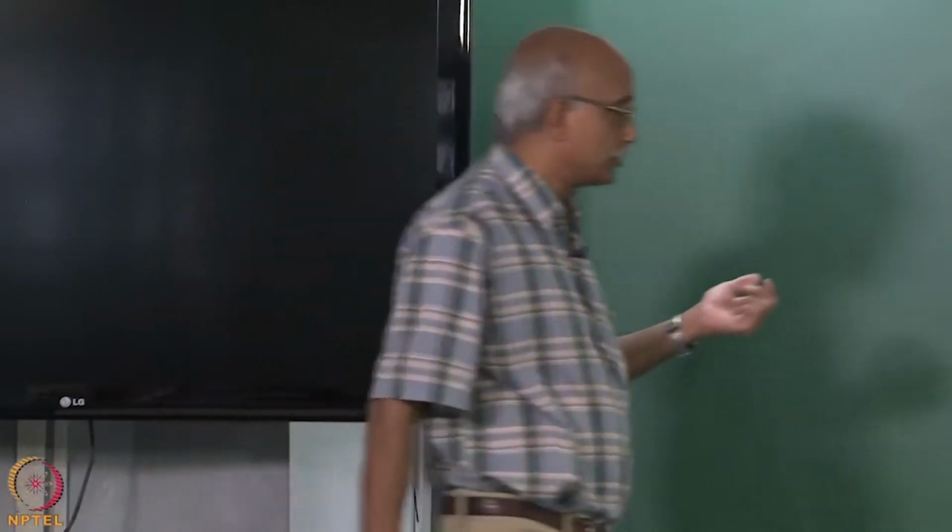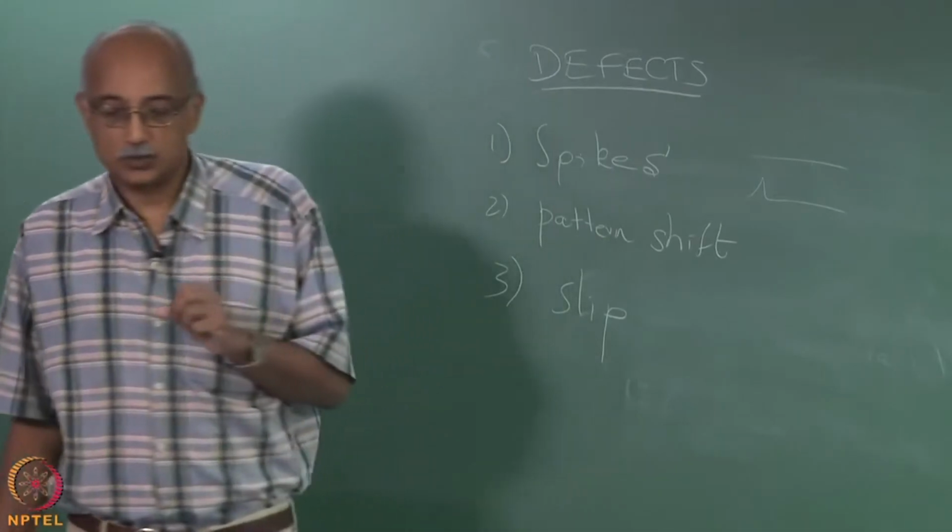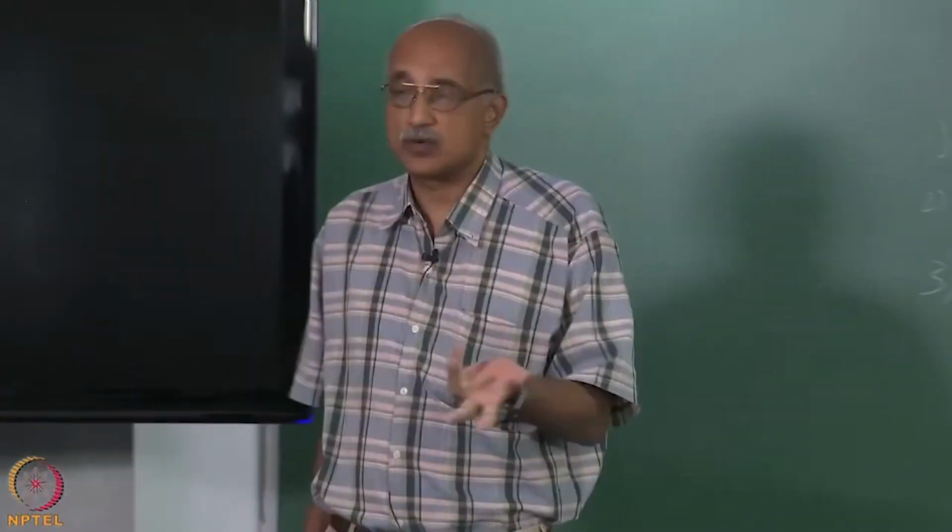And the only way to address issues like this may be to either change your reaction conditions, change the species that you are using for the CVD process, or in some cases by introducing a post CVD step which can take care of these defects.